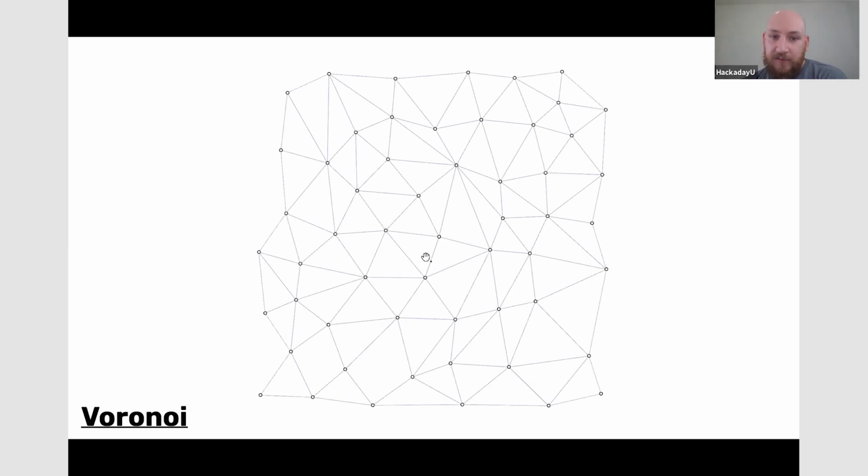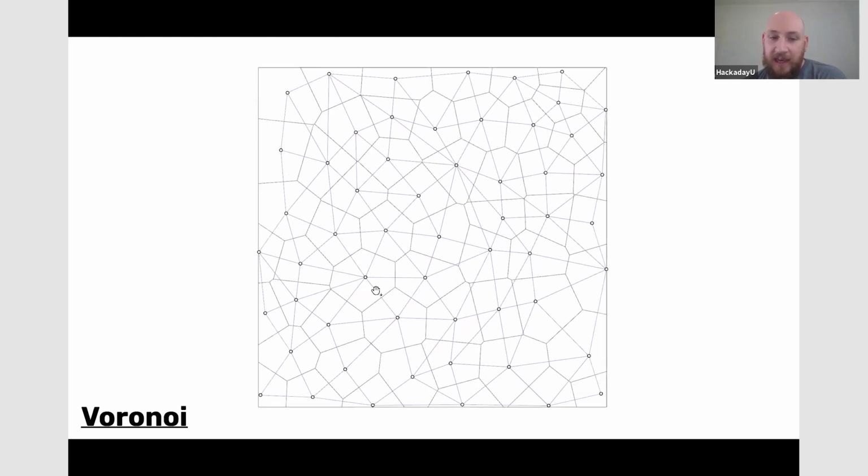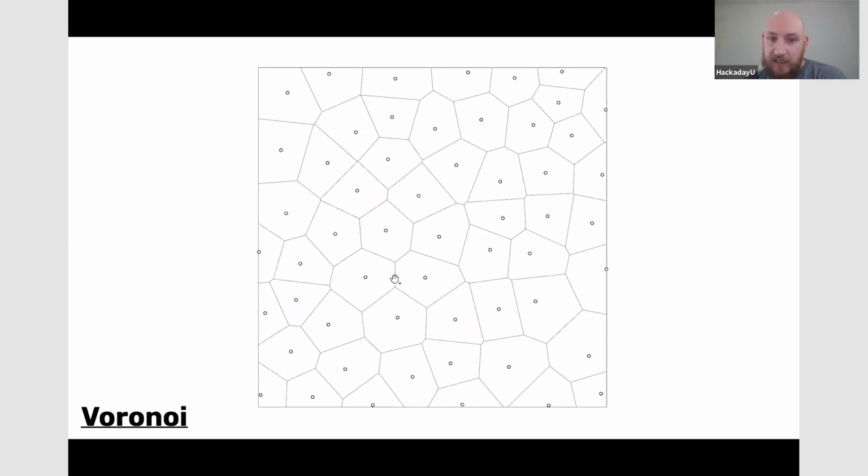And if those points find their nearest points and create curves between all their nearest points, and then you find the perpendicular bisectors of the midpoints of all those curves, and then trim them all, and then delete the purple lines, we get this sort of shell pattern. And let's turn off the lights. So this is a Voronoi pattern, and it's controlled by those underlying points. And I'm going to use a Voronoi pattern, which is just a ready-to-go Grasshopper component.